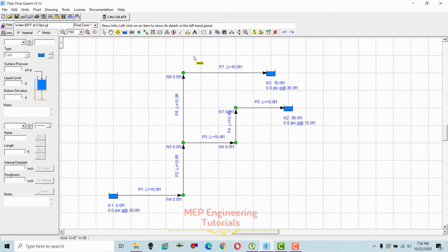In order to control the flow, 80 GPM at this tank and 120 GPM for this one, I'm going to use one flow control valve, either here or here, to control the flow across these lines. So if we have a total of 200 GPM in here, 80 will flow here and 120 GPM will flow there. First of all, I'm going to place a pump of 200 GPM.